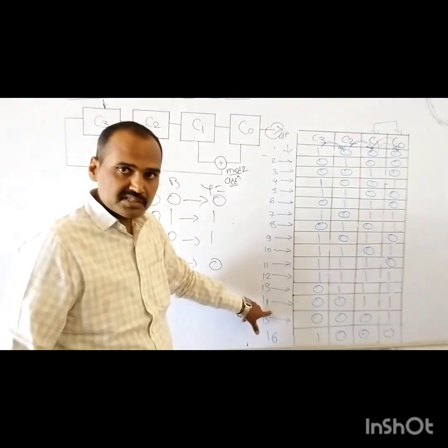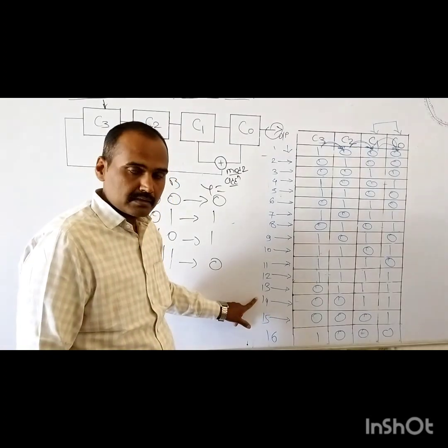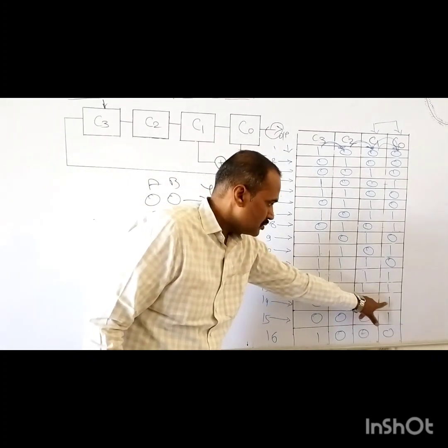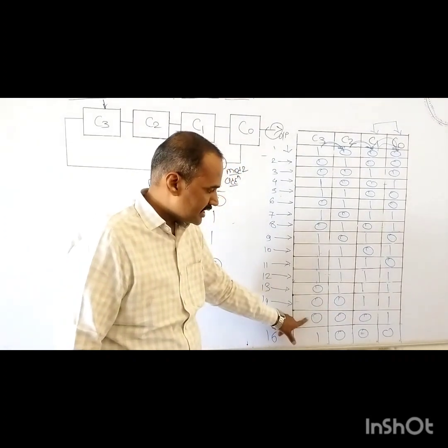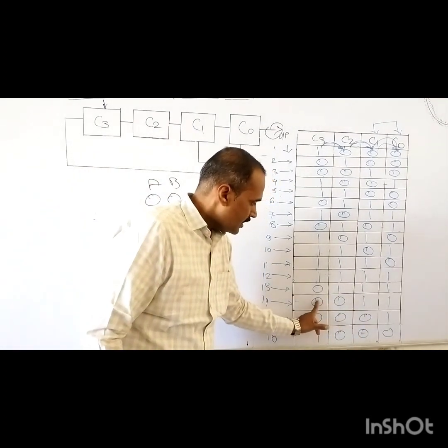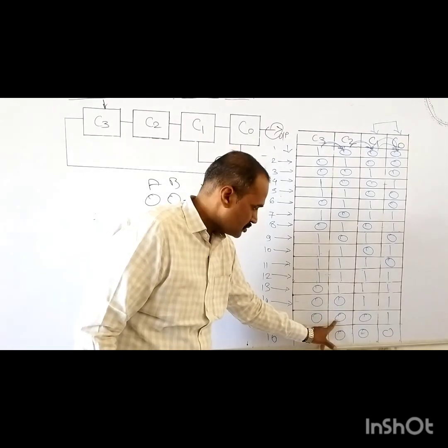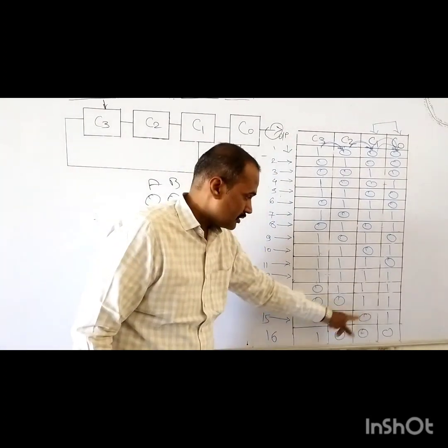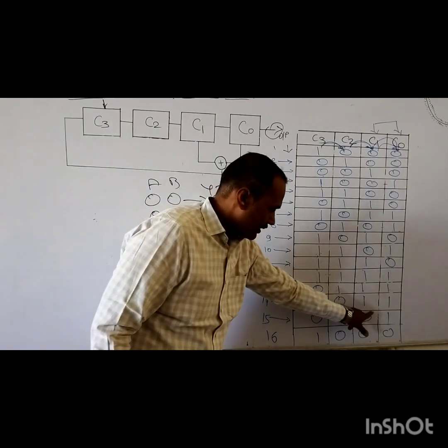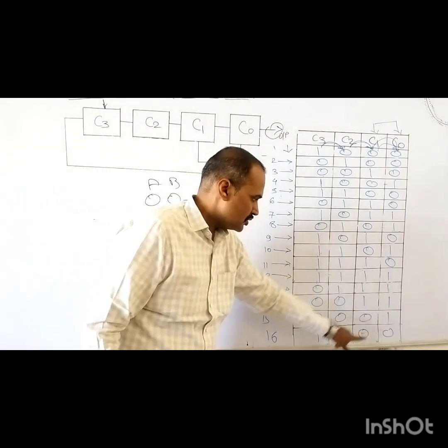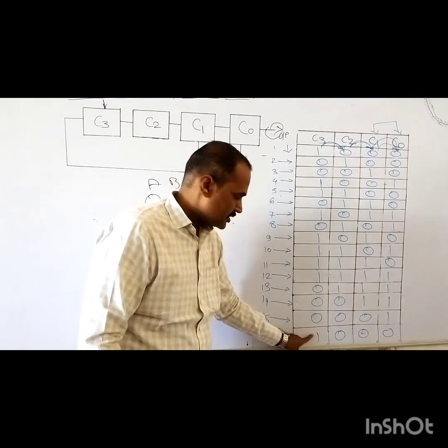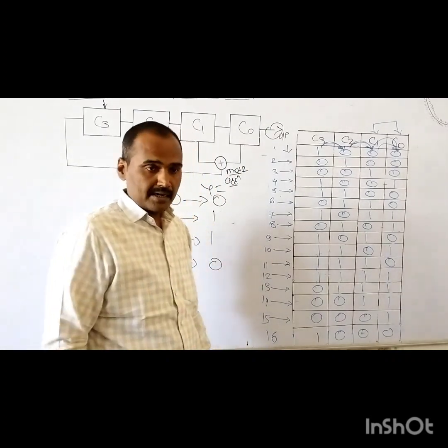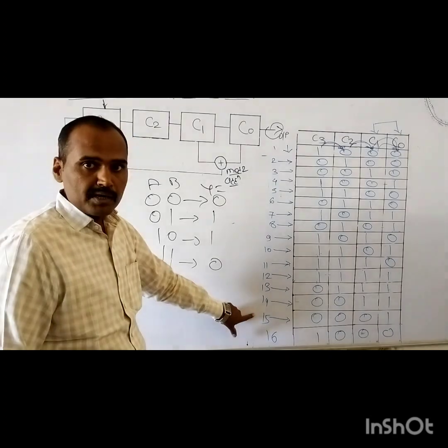How is that current status generated? As a result of clock pulse number 14. In this clock pulse number 14, C1 equals 1 and C0 equals 1, so 1 XOR 1 is 0, and these 3 bits are shifted like this. C3 becomes C2, so 0; C2 becomes C1, so 0; and C1 becomes C0, so it becomes 1. Now again, applying the mod 2 operation between 0 and 1, 0 XOR 1 is 1, and the remaining shifted bits are 0, 0 and 0. So we get the same code after clock pulse number 15.